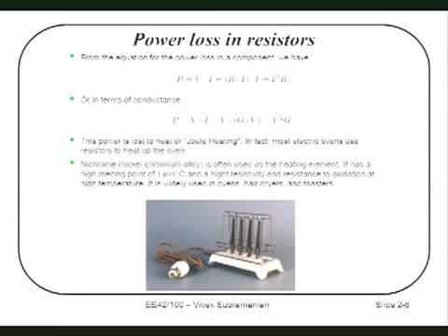Is that what happens when a light bulb burns out? Yes. So why does a light bulb burn out? When you are continuously flowing current through it, it's also heating up, and over time the material on that filament starts evaporating. And so it gets thinner and thinner, and when it gets thinner, what happens to its resistance? It goes up. So it's now getting hotter and hotter at that point, and ultimately it just burns out completely.